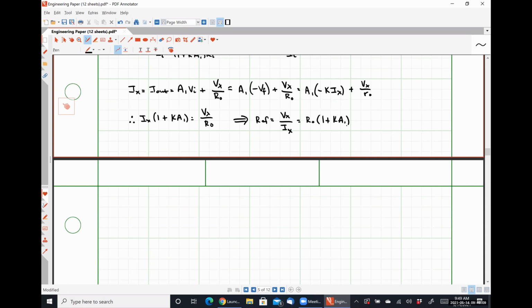For the feedback transconductance amplifier, it should be fairly obvious that we need a very high input resistance and a very high output resistance. There's a homework problem where you're just given pictures of 4 different amplifiers, and it was kind of hard to figure out exactly what was being asked. But if you look at the input resistance and the output resistance of those circuits, it tells you what kind of amplifier it would be best suited for. I'm just trying to make sure that I include that so that when you get to that problem, you have some idea of what you're trying to do.